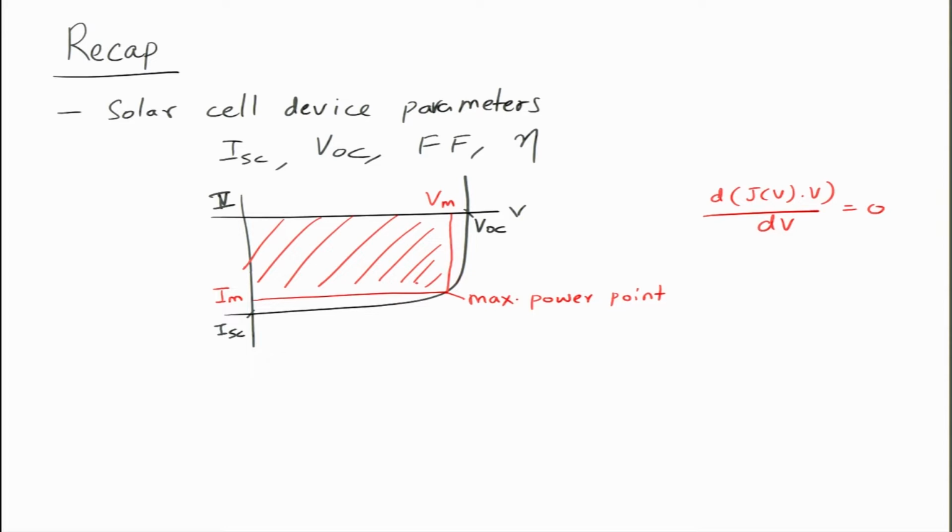So, this is the maximum power that you can draw out of a solar cell, which is within the experimental IV curve. The idea of materials and device engineering is that your aim is to make this curve as square or as rectangular as possible, which means that series and shunt resistance must be optimized. A bad solar cell would appear like this. If you now want to draw the MPP in this, it would correspond to something like this.